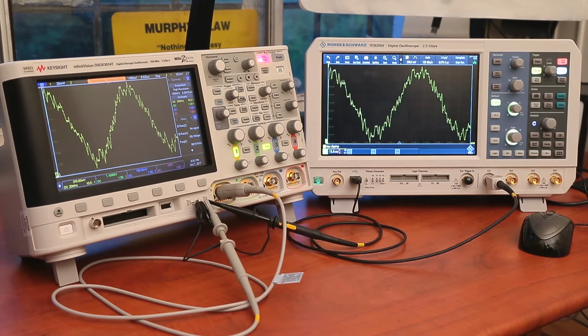The signal showing on the screen, on both screens, is being generated from the Keysight. It's one of their demo signals, which is a square wave with sinusoidal noise running on top of it. And I've tried to adjust the time base and the vertical sensitivity on both screens to get a very similar amount of detail in terms of full screen coverage, showing the same amount of the wave, and then I've actually run-stopped both of them.